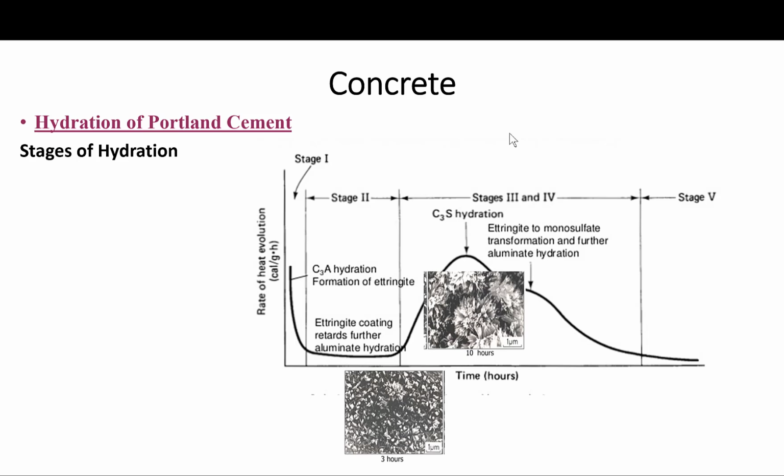What we will study also is the hydration process of the cement and how it relates to the end user, and what it means to the concrete professional, each stage of these. The stages of hydration. Once we add water, for a period, it's referred to as the dormant period right here, and what happens in each stage. Then we have what's called stage 3 and 4, the acceleration and deceleration stage. Stage 5 is called the steady state stage. And again, we will discuss what forms in each stage, and what every stage means to us. For example, right here we can transport, place and finish the concrete. Right here, strength gain starts, and the hardening. And after that, how the reaction slows down, for example, and what needs to be done, curing, and so forth and so on.